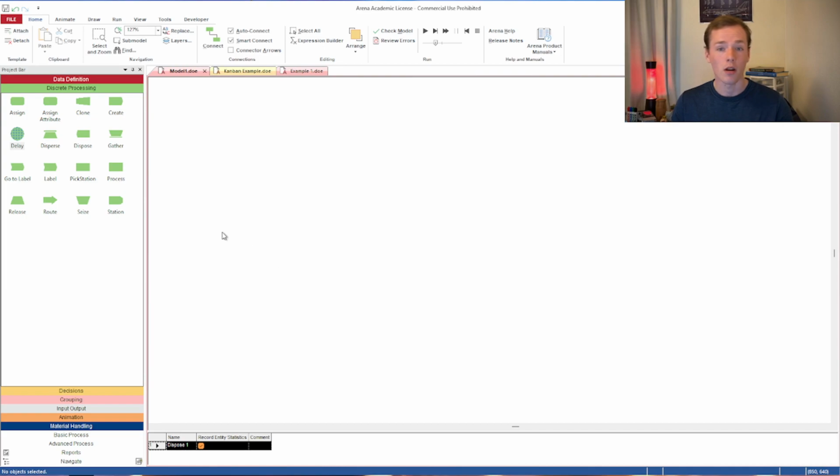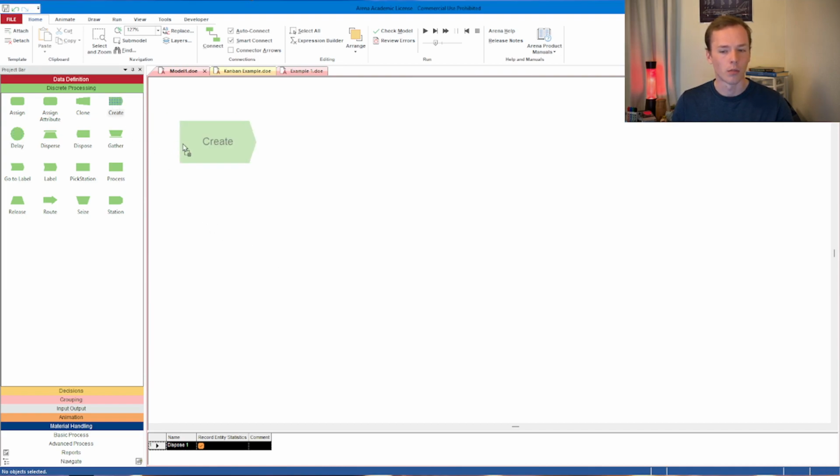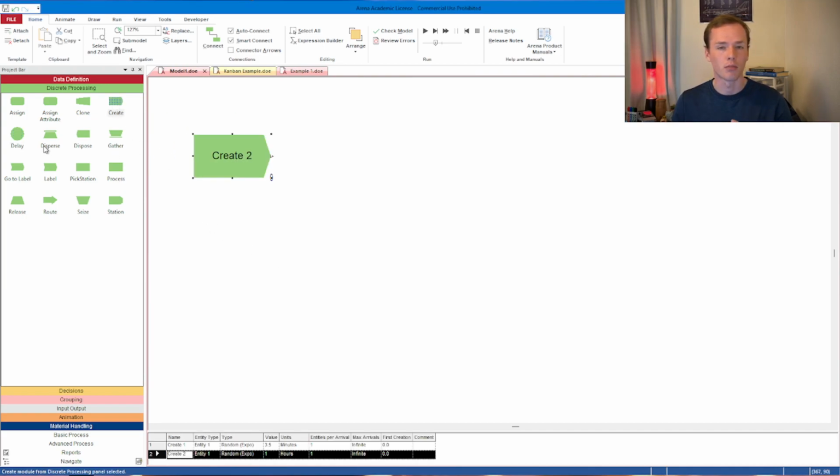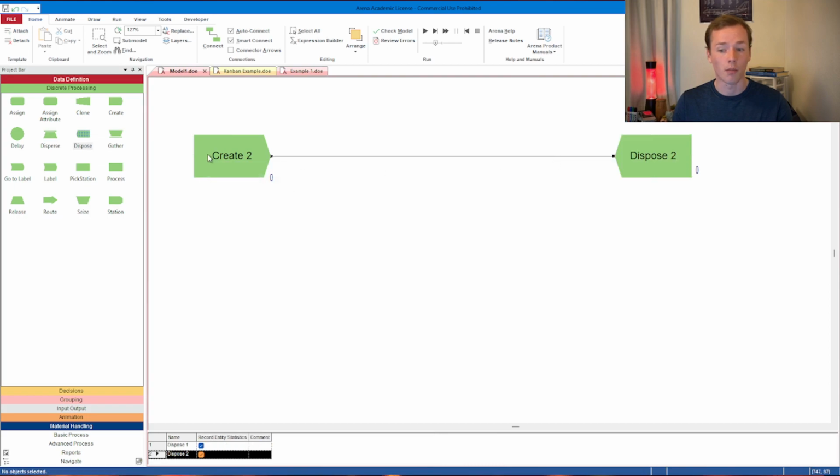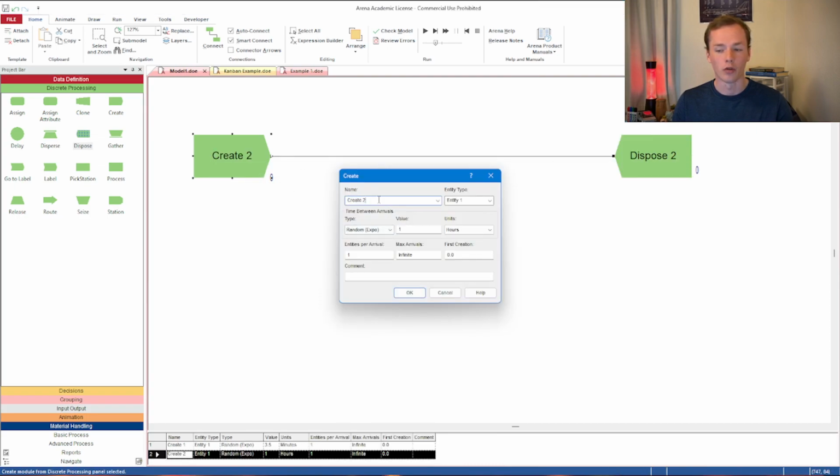So I'm hoping that you already know how Arena works a little bit in terms of create and dispose modules. The previous video in this playlist does explain that already. So what we're going to do is work on making a coffee shop. And we're going to assume that you're going to create entities and they're going to arrive with an inter-arrival time of roughly 5 minutes. So let's say that there's 5 minutes exponential time between arrivals, between customers showing up.